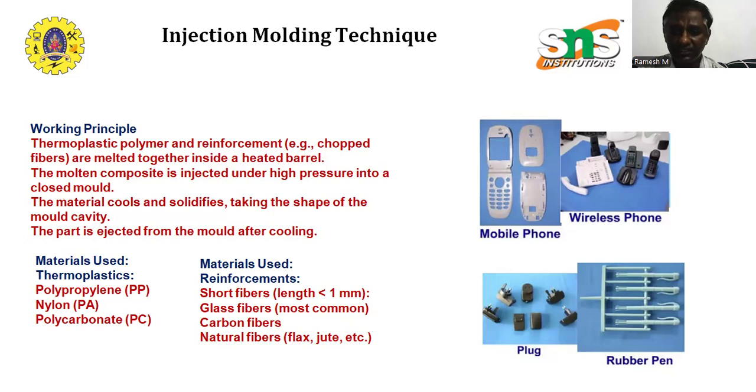The location of ejection pins is usually specified in the mold design, since their points have visible marks. Usually they are done from the core side, and it is usually mounted into the mold half mounted on the moving platen. The cavity is divided between the two mold halves in such a way that the natural shrinkage of the molding causes the part to stick to the moving half. When the mold opens, the ejector pins push the part away from the mold cavity.